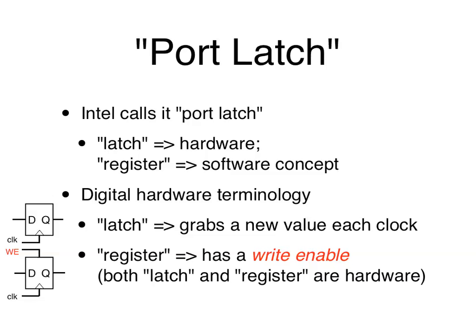But Intel did not follow that. Intel thought, we're just going to call these whatever we like. So they think latch means hardware and register means software. But if you read documentation in a TI datasheet, they don't call it port latch. They call it port register. Okay, just so that you know. This can be confusing, but I think it's important to get the terminology straight. Of course, there are a few other companies that follow Intel's non-standard usage, but you should know the standard usage is what I show here. So a port latch should be called a port register by everybody else, and TI does call it a port register. Okay.